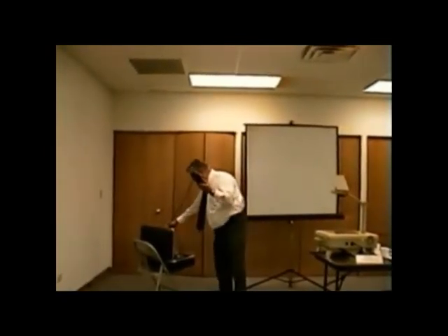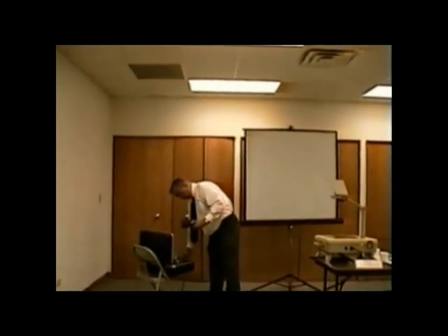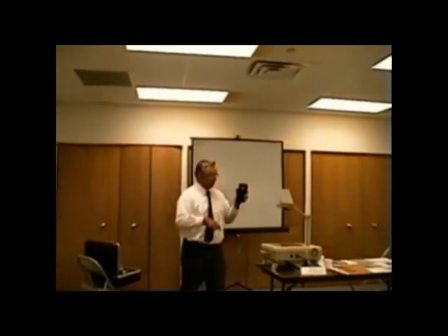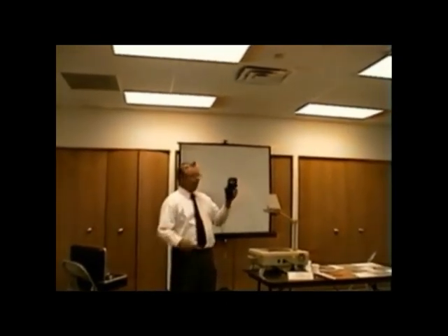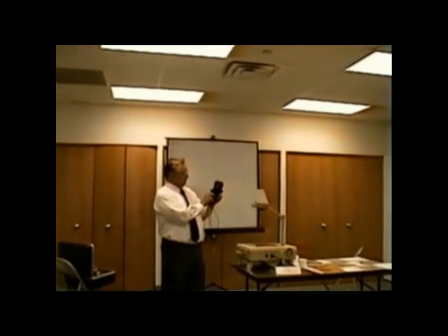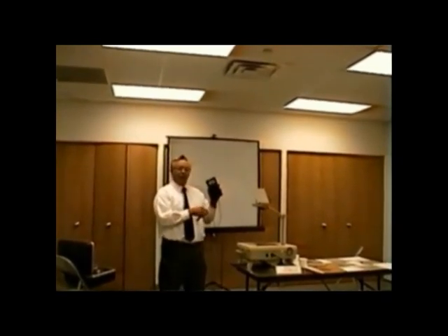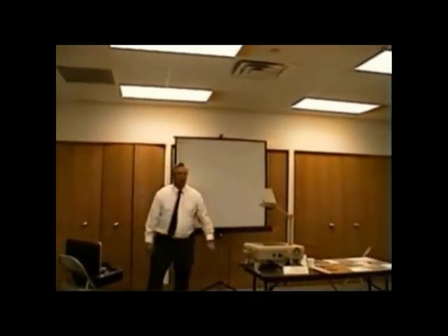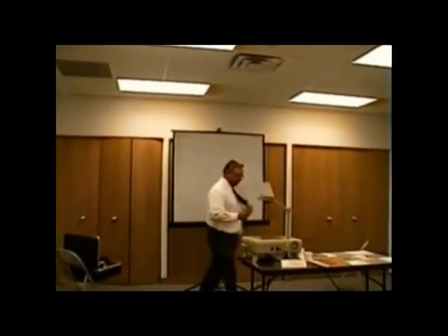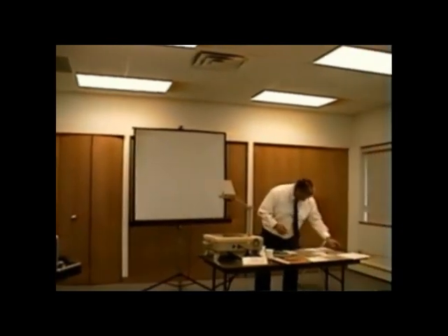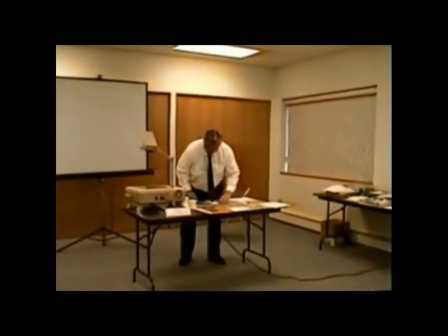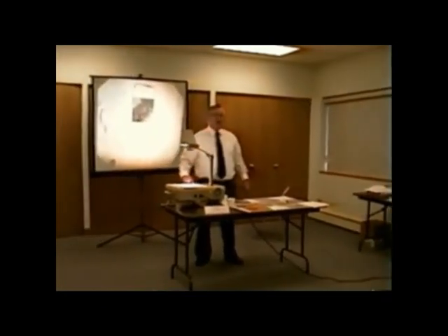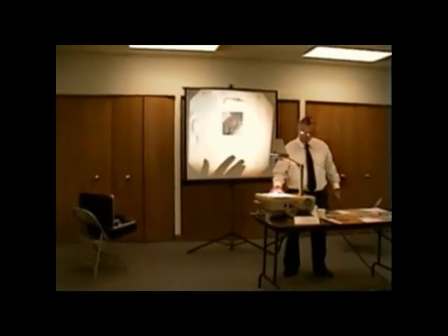and tell you that most digital voltmeters, and this happens to be an inexpensive one that we use here, have microamp scales. So you have to have a microamp scale. You have to hook it up the right way, you have to put it on the right scale. And you know, it takes you seconds to check microamps. I hope you understand that we have a flame rod. As a matter of fact, let's go to a picture here, it's up here. You got page 70 in your handout? Yes.